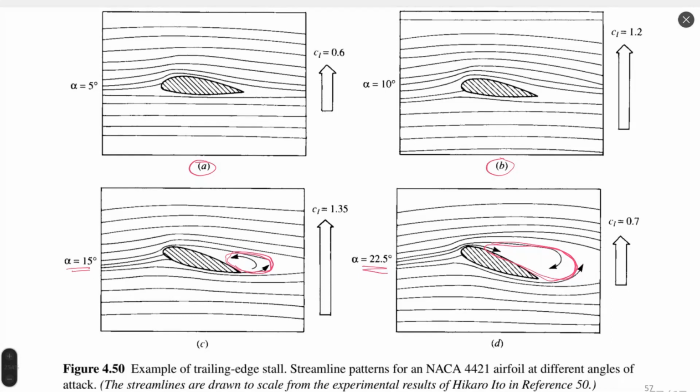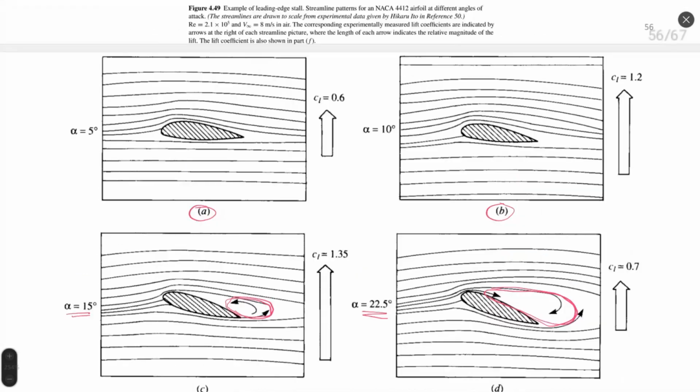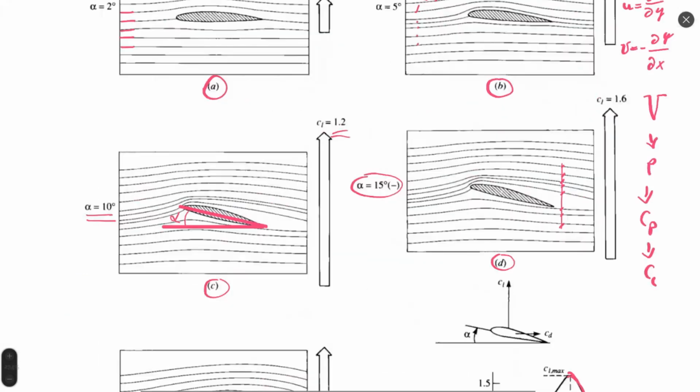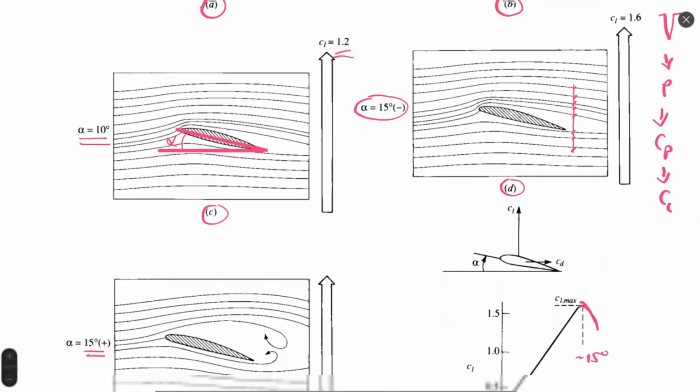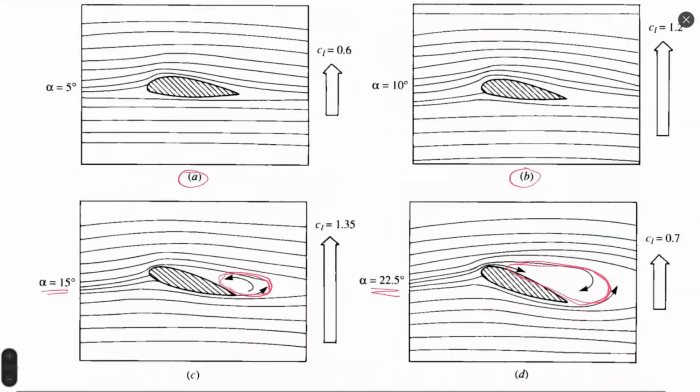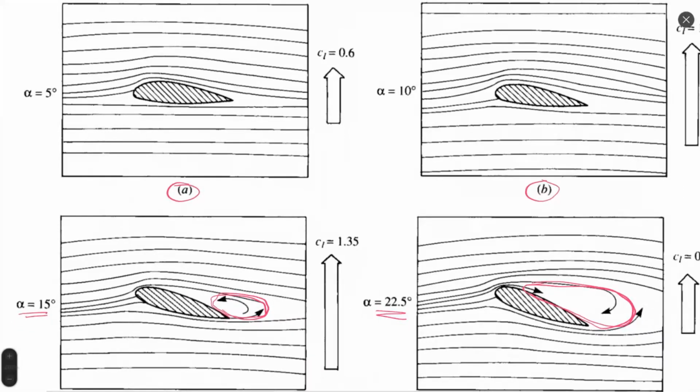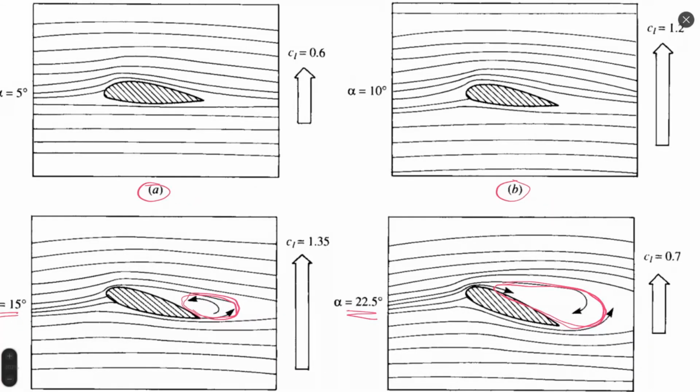I would like to remind you of the difference in performance between thin and thick airfoils. Usually thin airfoils are better for faster flight. Right? For high velocity, they support higher velocity for flight, but they have a smaller lift to drag ratio. Thick airfoils are better for slow velocity, and they usually have a bigger lift to drag ratio, so they are more efficient, but they fly slower. Thin airfoils are less efficient, they fly faster.